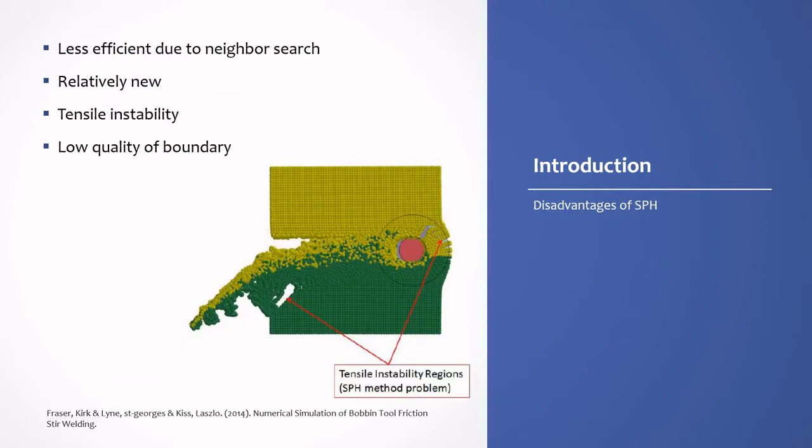Just as there are advantages to the SPH method, there are also some disadvantages. SPH is relatively new, so developments are still ongoing. In SPH, physical quantities are computed by an interpolation of the quantities of the nearest neighbor. This results in slower computation compared to other methods. Boundary conditions are also hard to implement. They do not appear in natural ways, and when the particles approach a solid boundary, they can create unrealistic interactions.